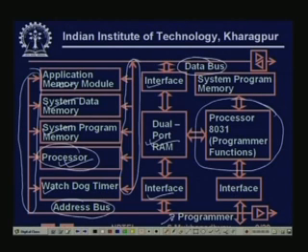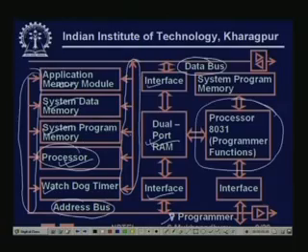interface with the programmer. A PLC system is typically interfaced with a machine, and industrial machines often run continuously. So you must provide mechanisms so that you are able to load new parameters, read status, and work with the system while it is working with the machine, without stopping it. For that, you need not only a dual ported RAM, you need another processor which will talk to the programmer while the main processor is actually busy controlling the machine, right. So this is what is done.